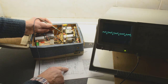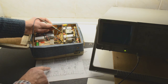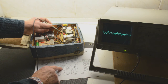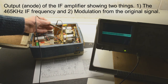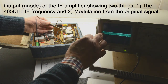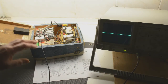Now we won't look at what's going in here with the diode, but instead we'll look at the output of the IF amplifier. Remember, there's only one IF amplifier here, oscillator mixer IF amplifier. So we look at pin 2 of that one. That actually comes out on this IFT up here. And that is the IF we're looking at.